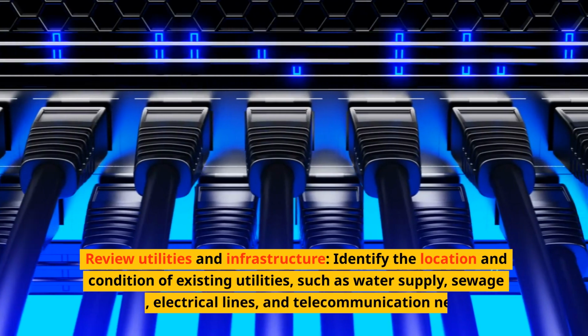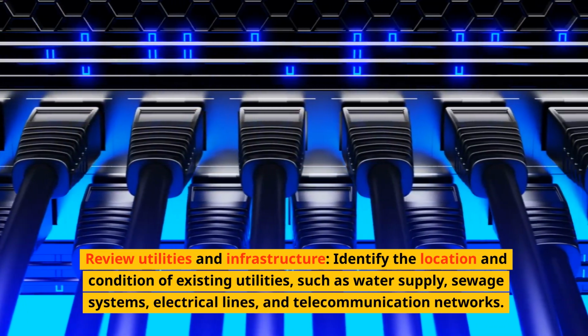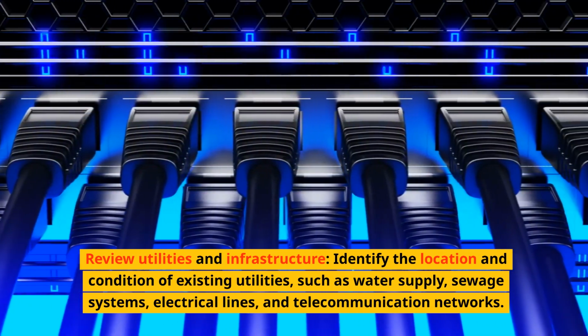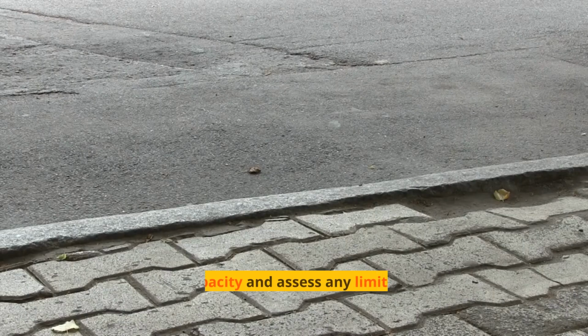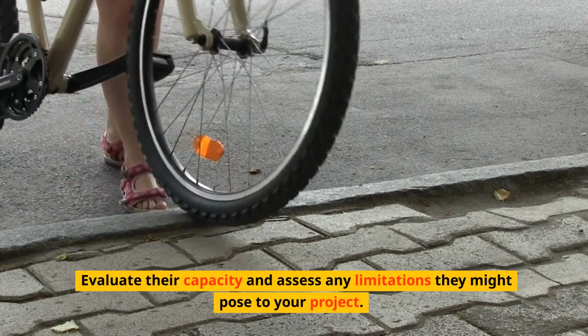Review utilities and infrastructure. Identify the location and condition of existing utilities, such as water supply, sewage systems, electrical lines, and telecommunication networks. Evaluate their capacity and assess any limitations they might pose to your project.